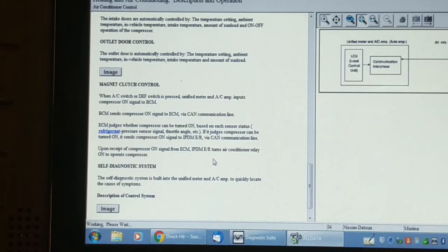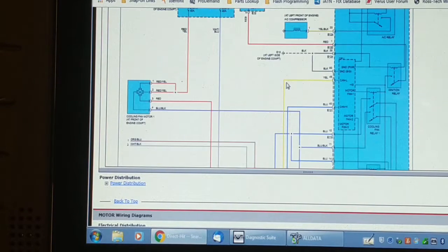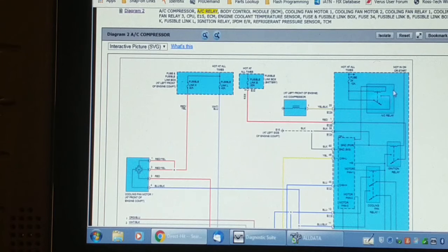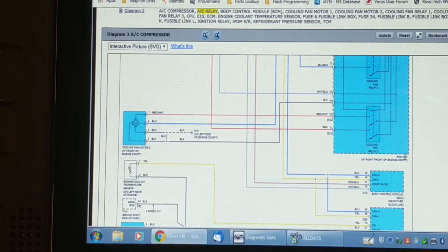So where is the relay? I'd like to look at it. I'd like to check the pins on it, maybe swap it, but it appears it may be integrated into the intelligent power distribution module. Not given up yet. Well, so far all indications are that the relay for the AC compressor clutch is not serviceable, and it's in that intelligent power distribution module, engine room at the right front corner of the engine compartment.